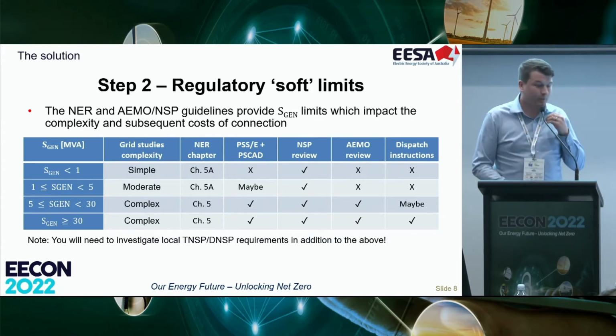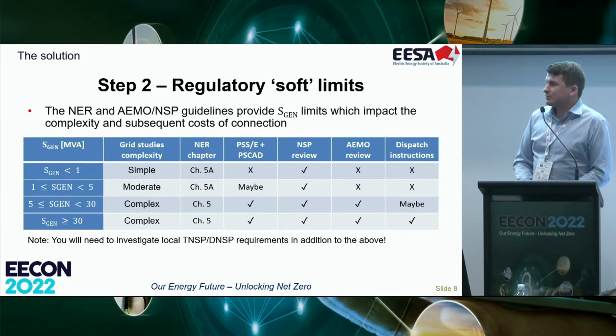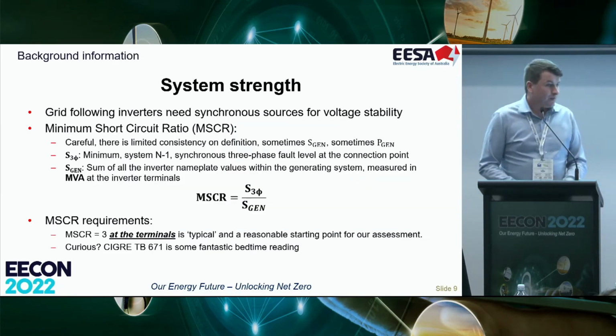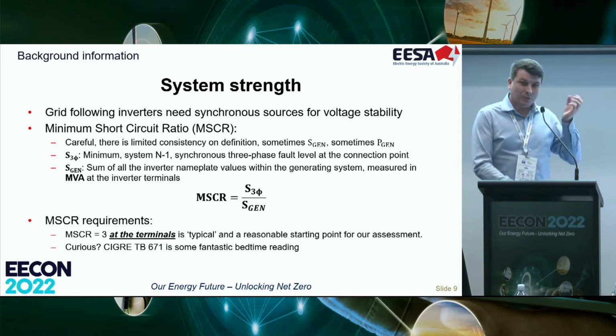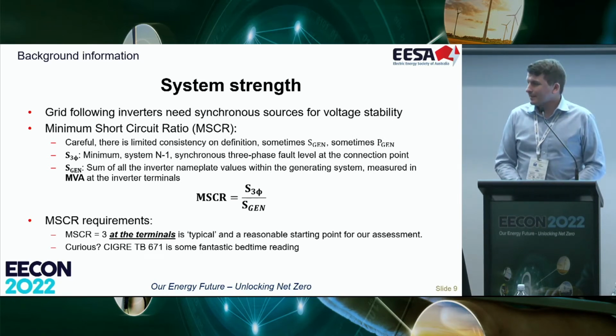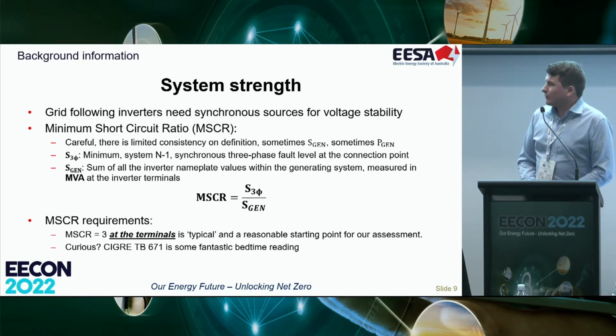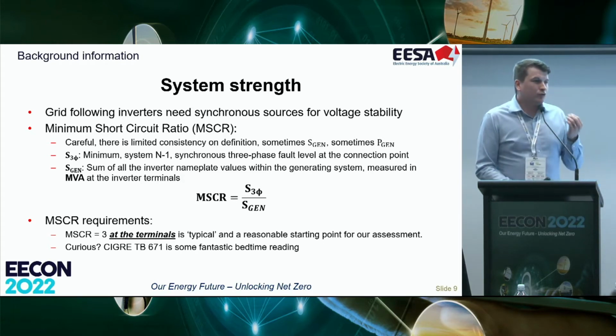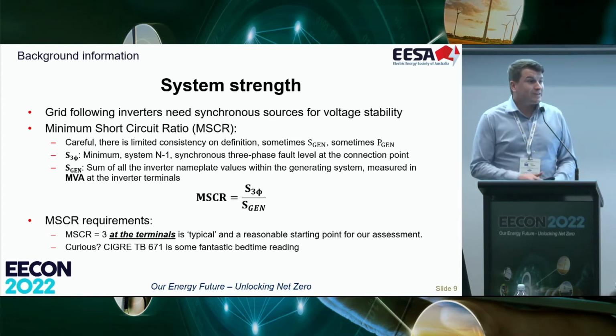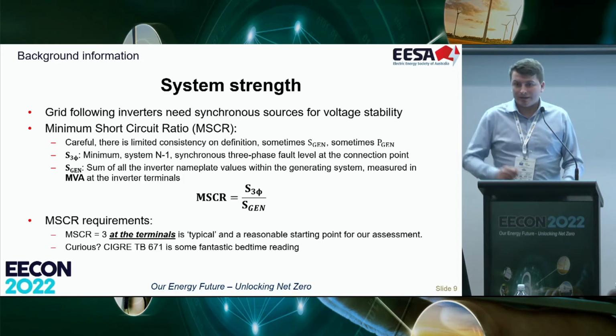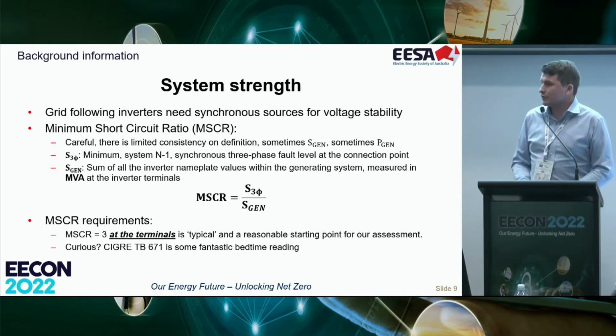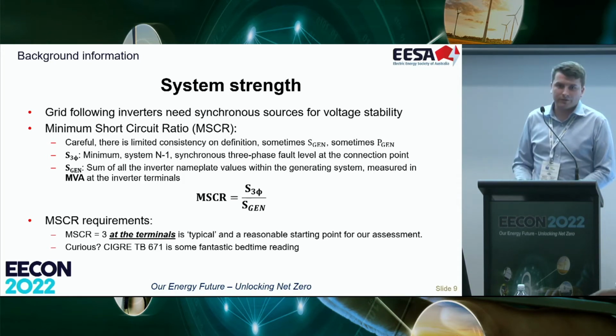There's a little bit of background we need to talk about here, which some of the presenters before me have touched on, which is system strength. Here's also a good seed for a future question. But as has been mentioned at this conference quite a few times, grid following inverters require some level of synchronous fault level to remain synchronized. If there is insufficient fault level, they will not be able to remain synchronized.